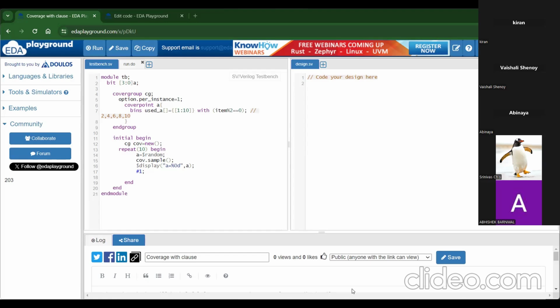So this connection we need to do where exactly this is residing. For example, it is present in the env of the test bench in the UVM. Then in the environment, in the connect phase, we need to connect these two by using the hierarchical handles. And then a coverage collector can also be instantiated inside an agent, because in the agent we will get all the protocol specific activity, right? Means from the driver it is out. It depends on your architecture basically. It can be inside the agent or it can be outside the agent. It all depends on your architecture.